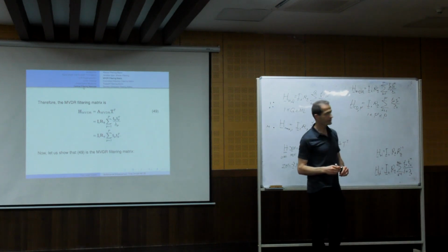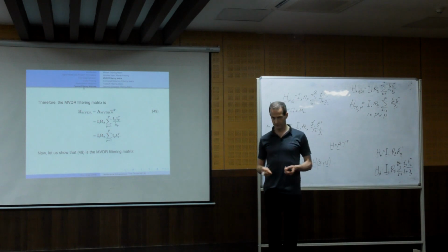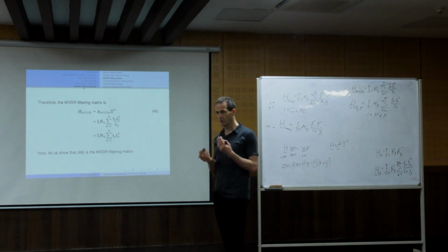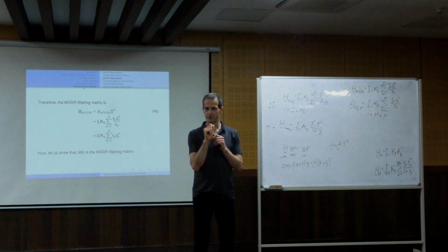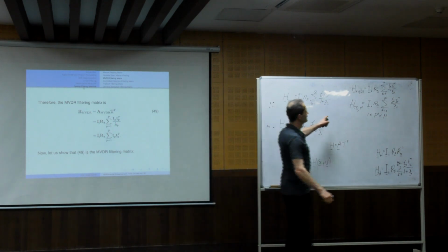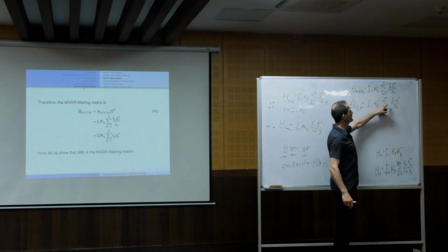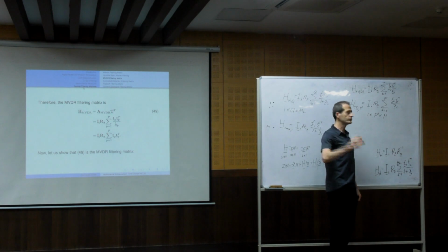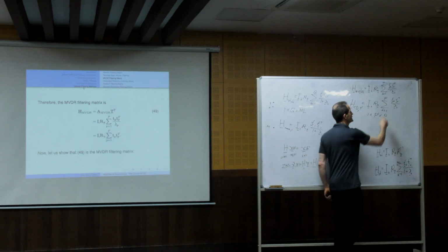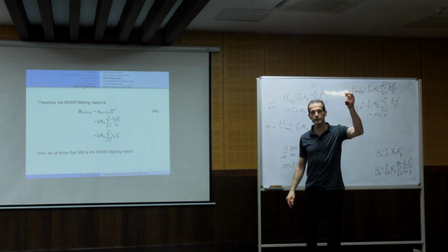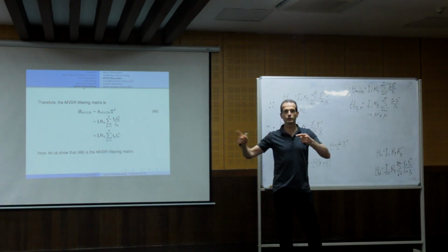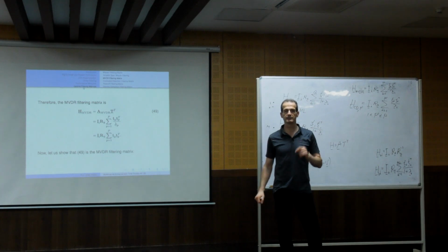So this filtering matrix enables us to control in a smart way between noise reduction and speech distortion or signal distortion by using a parameter. And you see, it's smart because it's easy to control using the parameter. We just take the summation until some components, because these components are ordered in the best way according to decreasing order of the trade-off between noise reduction and signal distortion.